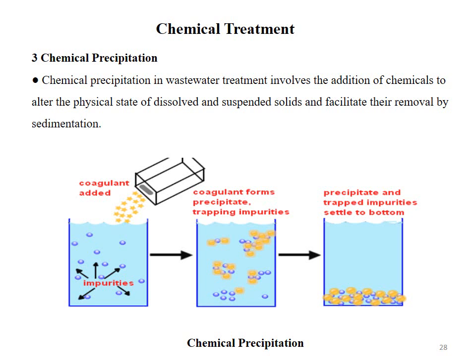डिमॉन्स्ट्रेट किया गया है that a contaminated or wastewater is containing some impurities, and then a coagulant or any precipitating agent is added in this water. Then this precipitating agent combined with these impurities and convert them into a material which can be easily settled down. These precipitates are then settled down as impurities, and rest of the water is removed out from here.